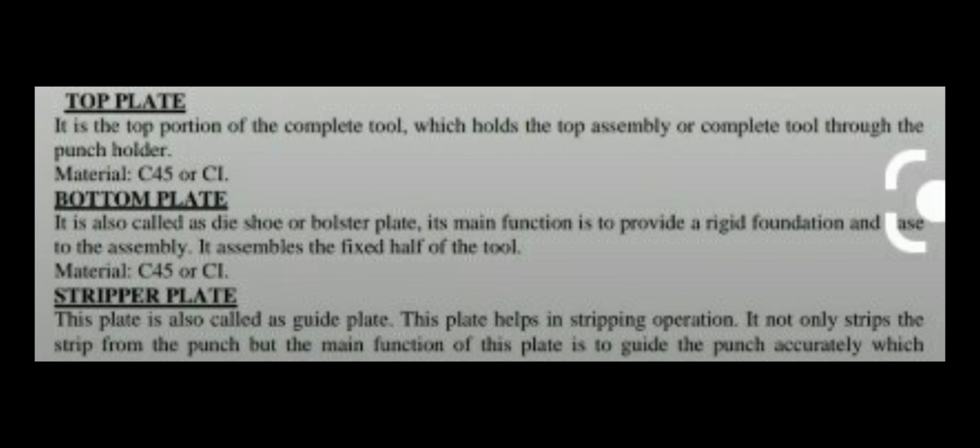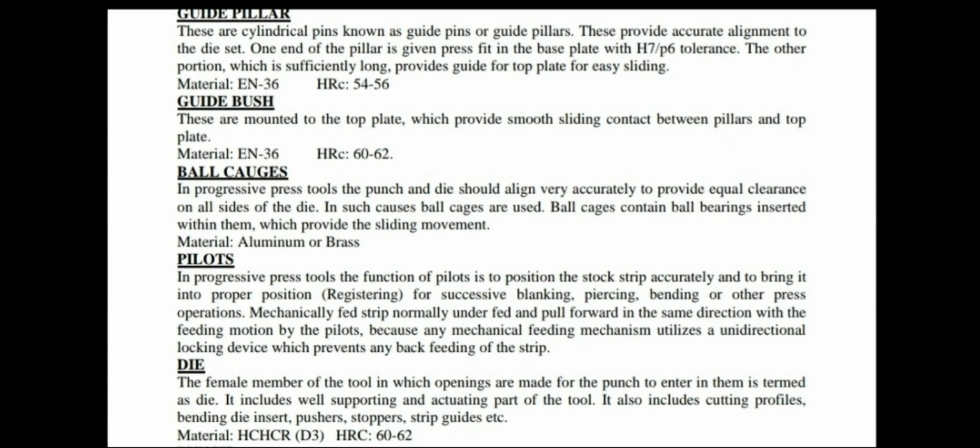Then the stripper plate is also important. All of you know, this plate is also called the guide plate. This plate helps in the stripping operation. It not only strips from the punch, but the main function of this plate is to guide the punch assembly. Then the guide pillar is also an important part.